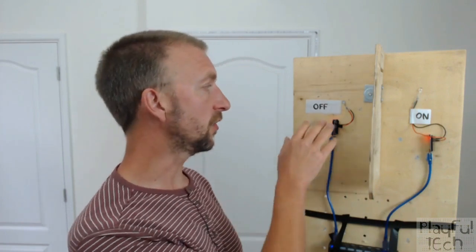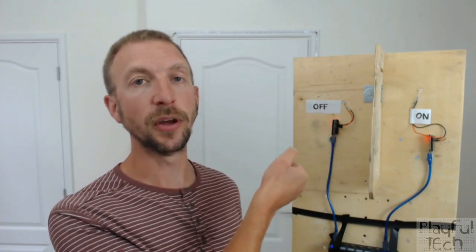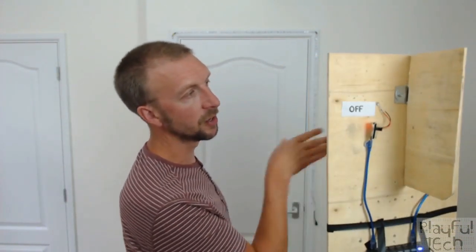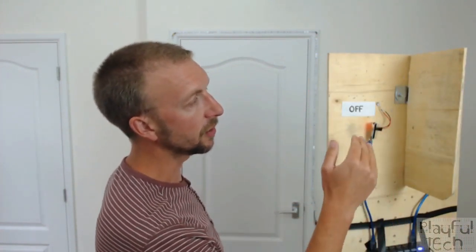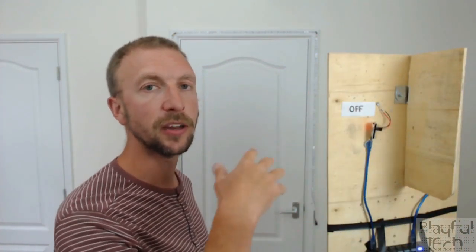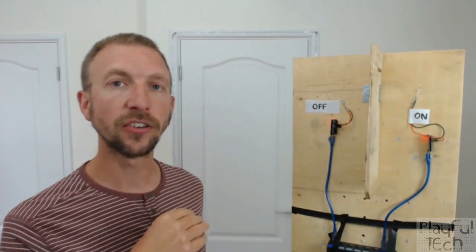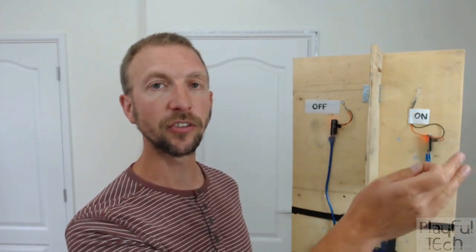The Arduino on the right is going to be making this infrared LED blink using the on pattern over and over again. So it's a little bit like there's someone here holding down the off button on a remote control, and there's someone over this side holding down the on button and just continuously pressing it down. Now you'll also see down the middle of the board I've created a kind of primitive barrier here so that it's not possible to see the blinking pattern of both LEDs at the same time. Remember that infrared works by line of sight, so wherever we're positioned here we should be able to see either one signal or the other, but not both.